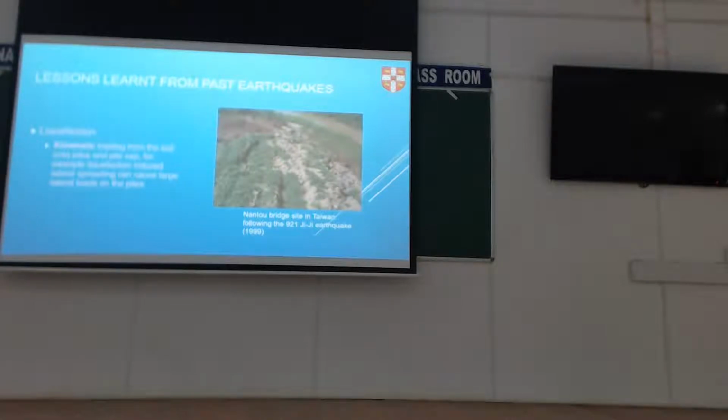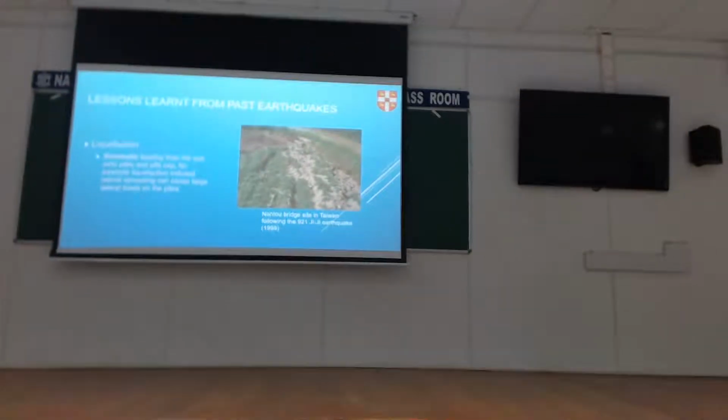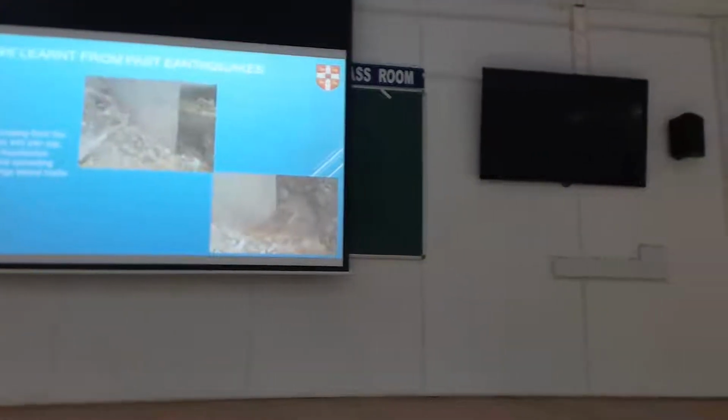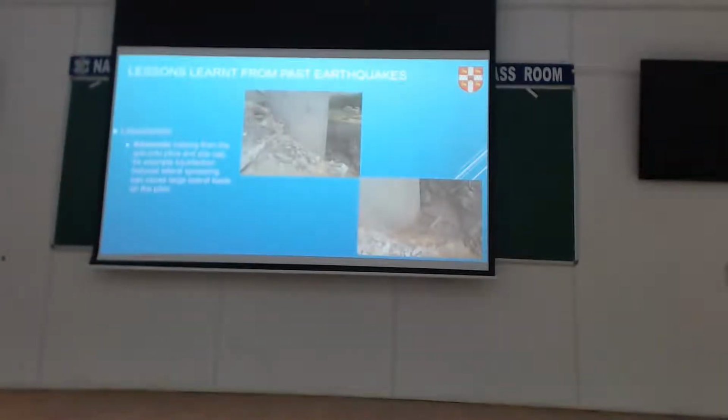Because of liquefaction-induced lateral spreading, as the soil flows past the pile, it wants to take the pile with it. And here is a perfect example of that. The pier of the bridge standing in the way of soil. One thing as geotechnical engineers you must learn is never stand in the way of moving soil. It gets very cross. And the way it shows that is by applying passive pressures. If you allow it to move away from yourself, then it's quite benign because you'll only mobilize active pressures. But if you put stuff in its way, it gets cross.